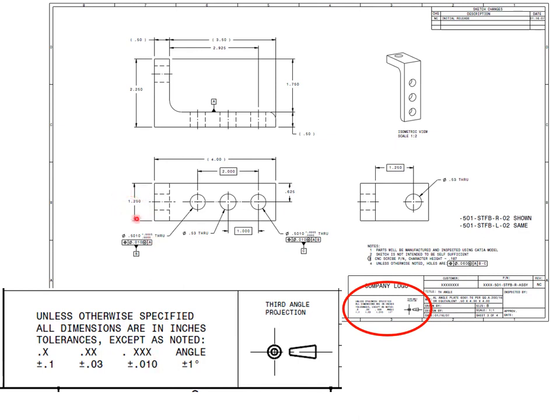Now again, I'm looking at my mistakes. This is too tight. I should have used 2 decimal places. 2 decimal places is about 0.030, or 30 thousandths. It's about the thickness of a credit card or an ID card. If you only see 1 decimal place, then you can be off by 0.1, which is the same as 0.100, or 100 thousandths, which is about the thickness of 2 compact discs. A compact disc is about 50 thou, so 100 thou would be 2 compact discs.